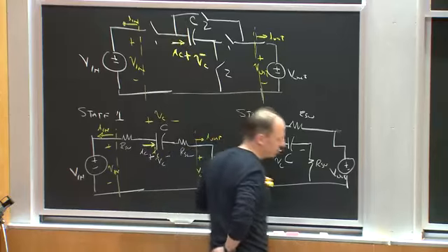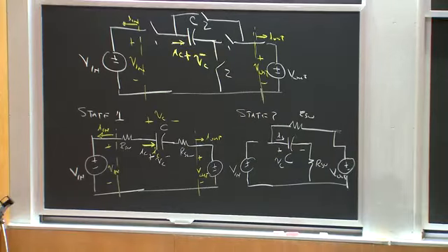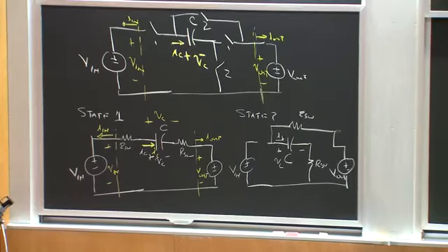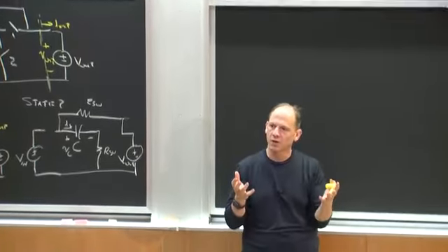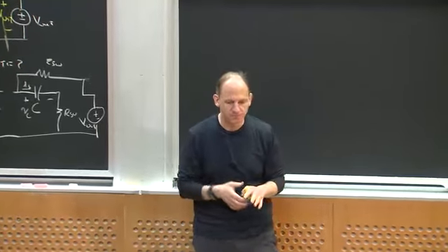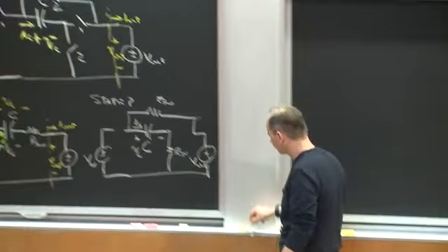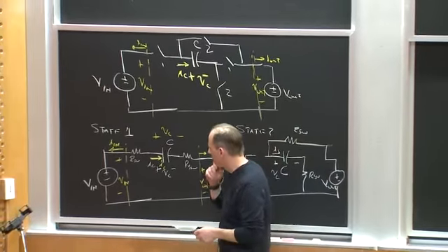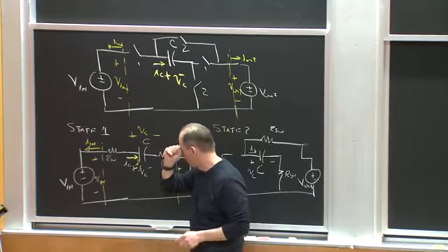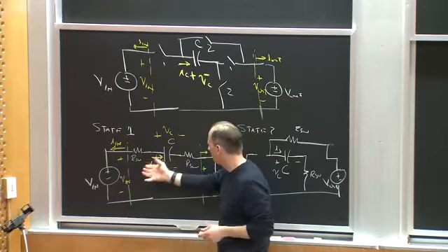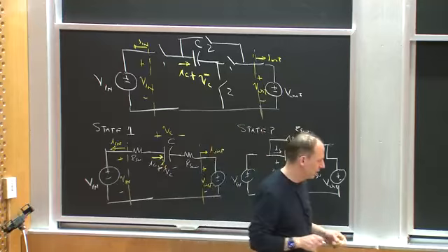Okay? And what I would like to do is track the charge flowing through this converter, which is going to let me understand what its conversion ratio is. Analyzing any switch capacitor converter more or less comes down to the process I'm following. There are ways that we can organize it to do the general case, but let's just think about this case. Let's suppose that when I close the switches, and I have some switch resistances, the values don't matter, but let's ask, what does the final voltage of the capacitor end up at?